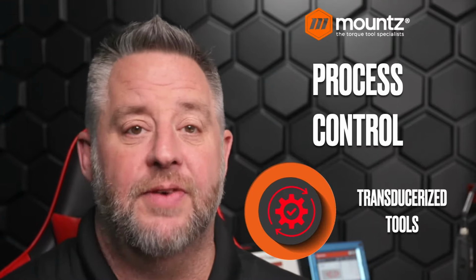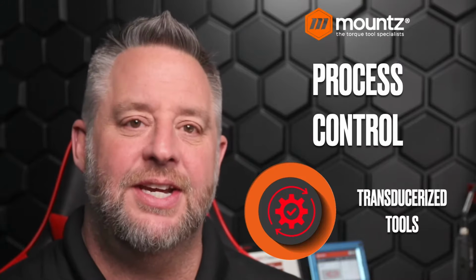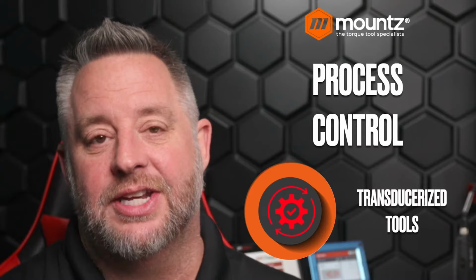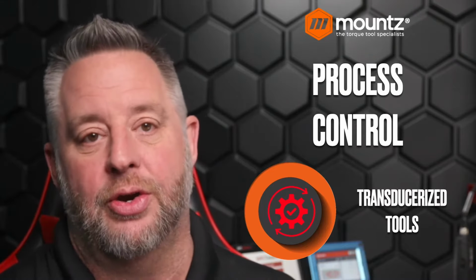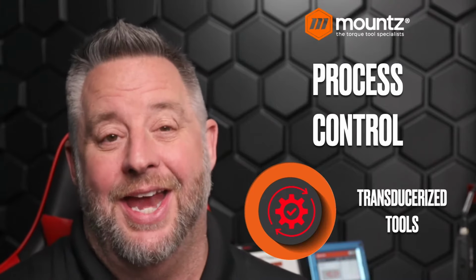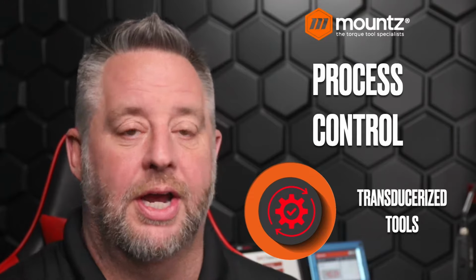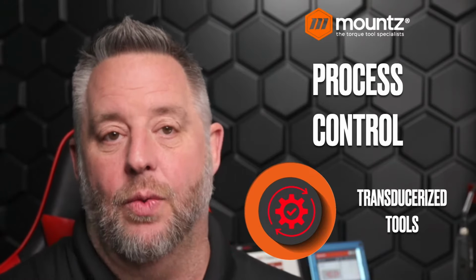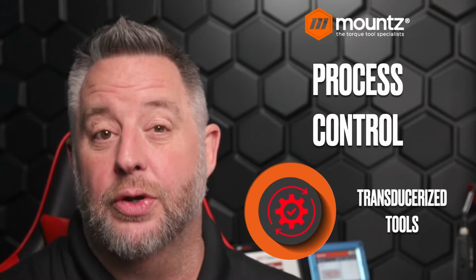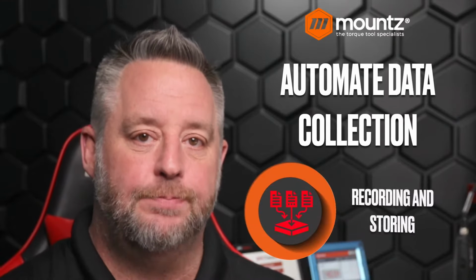Next is going to be the use of a transducerized tool within the process. And what this means is that we have a sensor that is built inside of the tool, and it's giving us the real-time monitoring feedback of the torque that's happening. And again, that is really vital in making sure that we're hitting our correct torque values, that we are within our specific torque tolerances that we may need. And all of those can be programmed for a specific preset, as I mentioned.